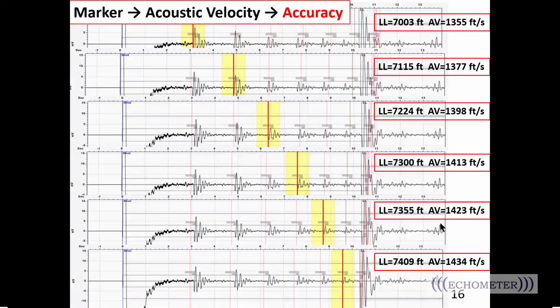Well, normally when you drill a well, you have an initial pressure, initial temperature, and the Earth's temperature pretty much stays constant at the bottom of the well. You don't really see a change in it. So what we assume is that you enter the bottom hole temperature from when it's drilled, and you enter the surface temperature that's close to the mean annual temperature of the surface.